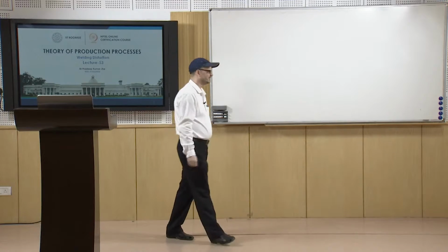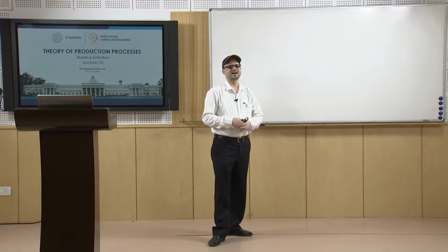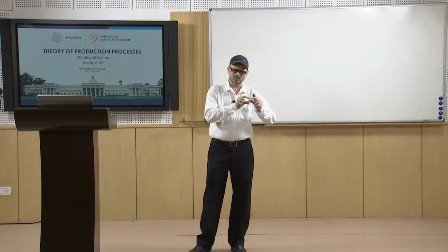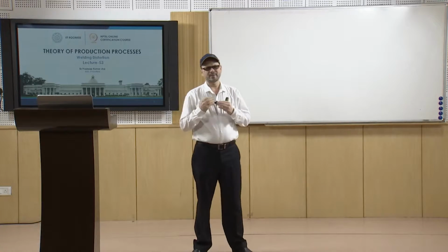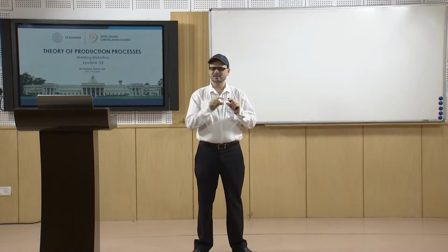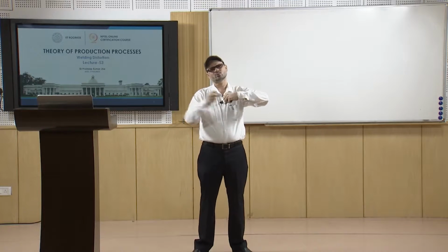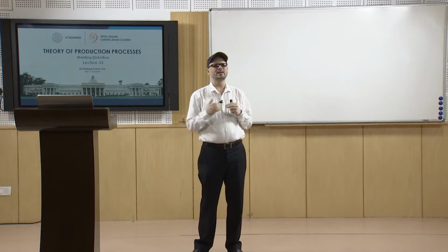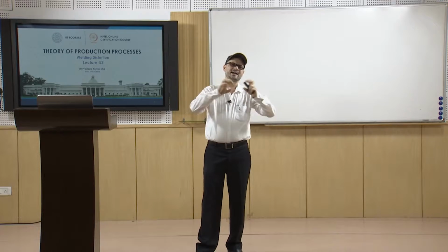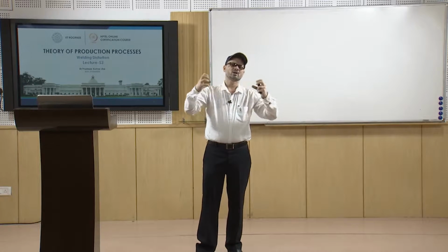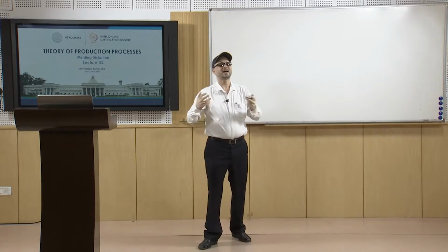We have already studied how, when you are welding in the middle portion, the weld tries to expand and the adjacent portion tries to resist it. Similarly, while cooling, it will try to contract and the adjacent metal will resist that.